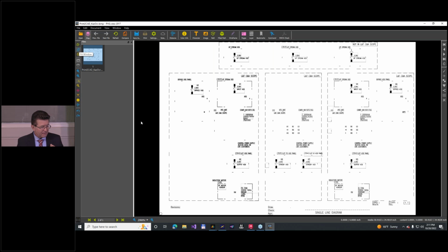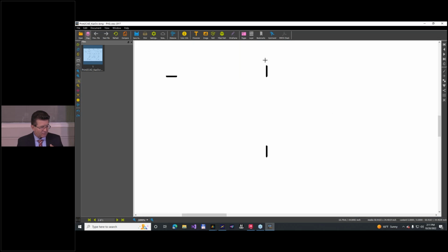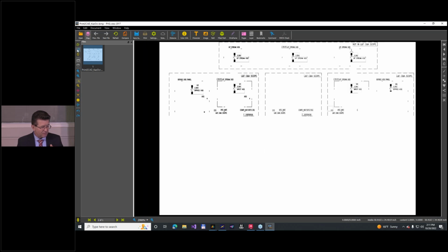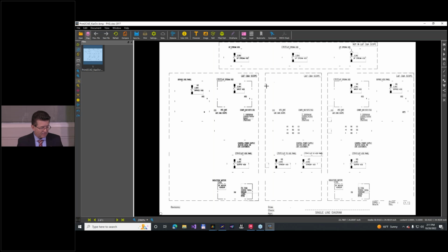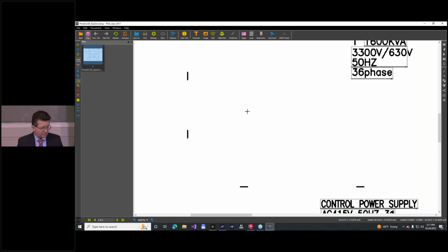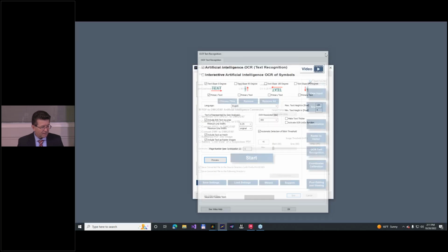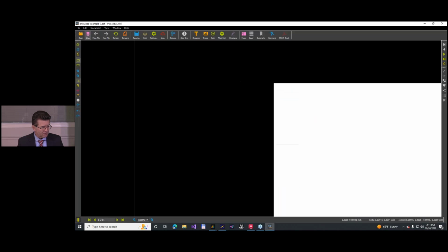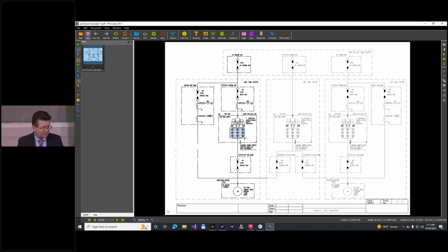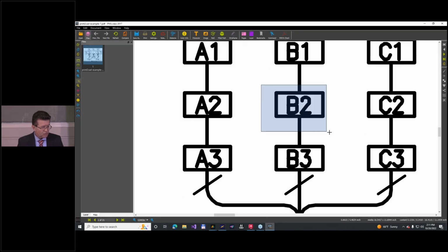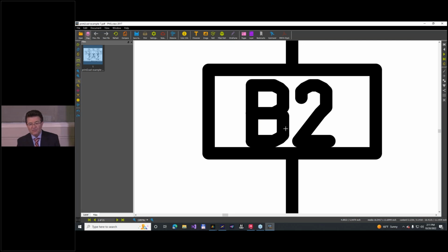You will see later we have no problems with it because we know that this belongs to the dash dot line. But here, see, this text almost fully disappears. Why are you not able to recognize this text? The reason for it is the following. I show you something. Here, if you view this input, you can see that somebody defined here two big line widths to the lines.